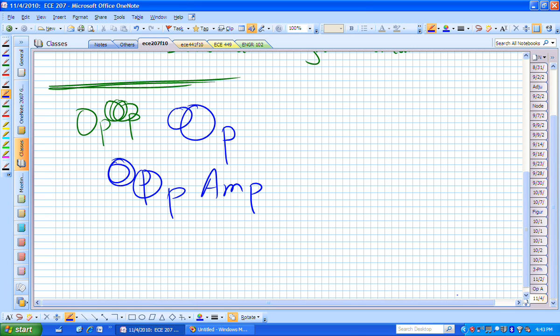Now what we're going to do is feed this through some feedback resistors down to ground. We'll call this R2, this is R1, here is our ground, and now this non-inverting node is what we will apply our input voltage to. Here is our output V naught, and we can connect a load to that.